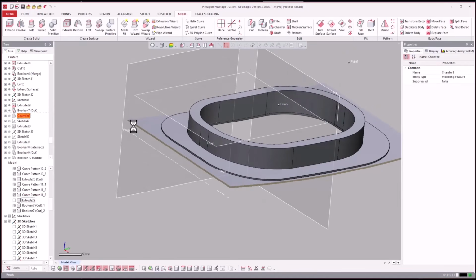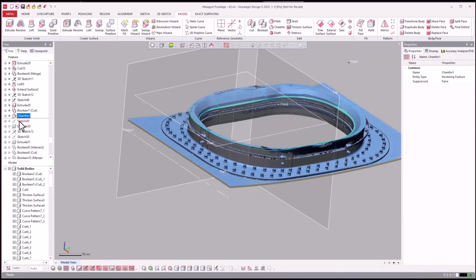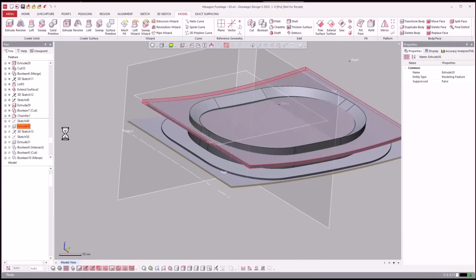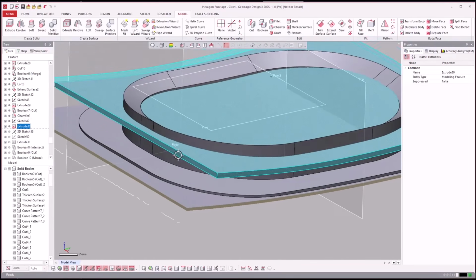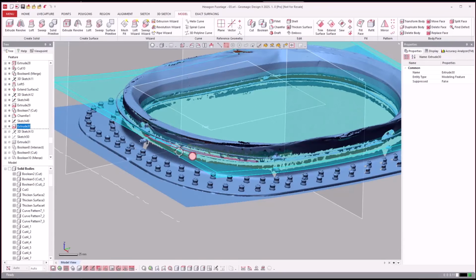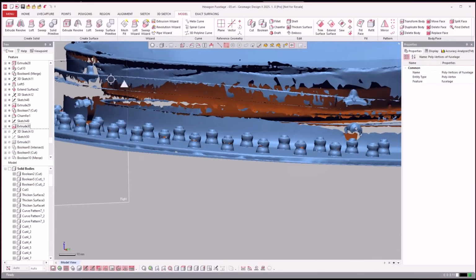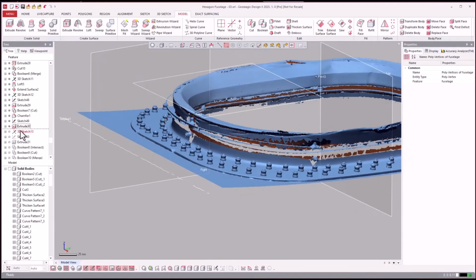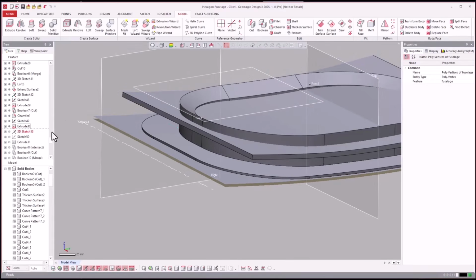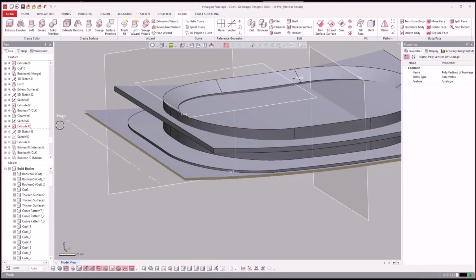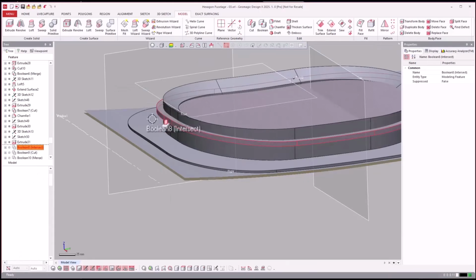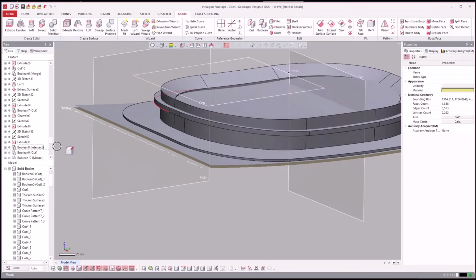we added a chamfer, so you can see there, roll forward, and there was a tab around the outside. If I hide the solid, there is this guy right here, not a tab, but like a band that goes around the outside. So we went ahead and did an extrusion. Then we extruded from the top and did a Boolean intersect between those two shapes to create this.